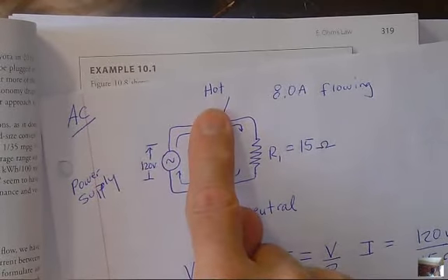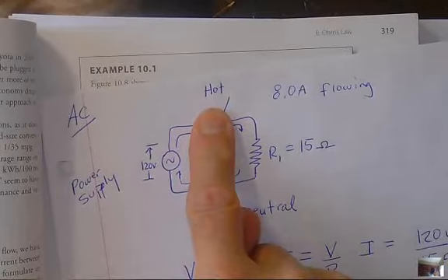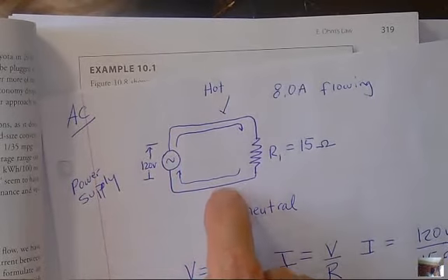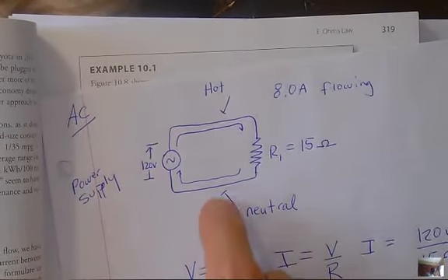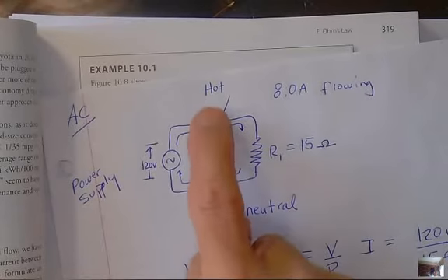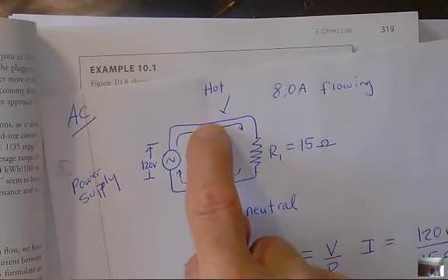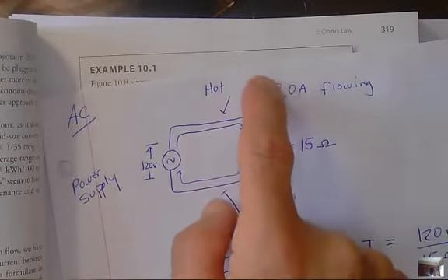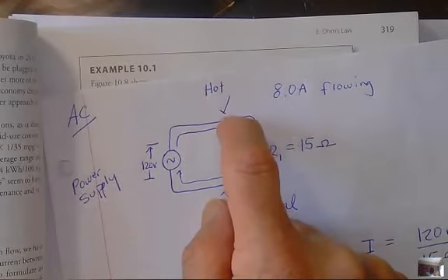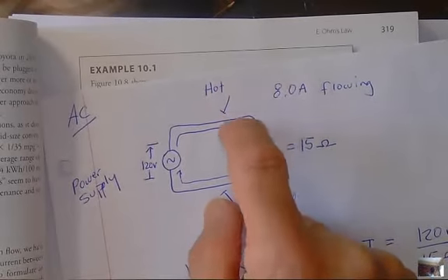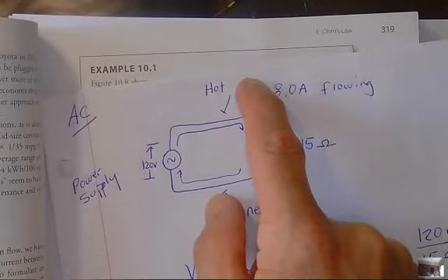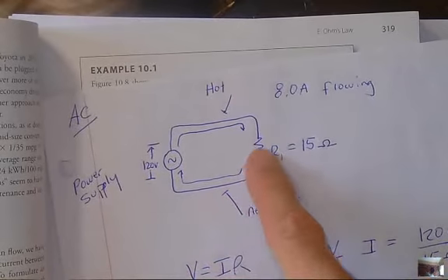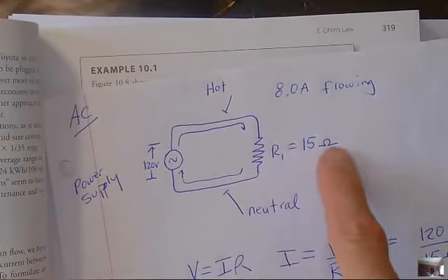If I cut off the hot and I touch the neutral to the ground, I shouldn't get any potential difference. If I have the hot on, it's not the hot by itself that's going to electrocute me. If I touch the hot and then I touch something else, I become the conductor. I become a pathway for the electricity to go to the next thing, and that's how I get electrocuted. I kind of become the resistor, and I cook instead of the toast.